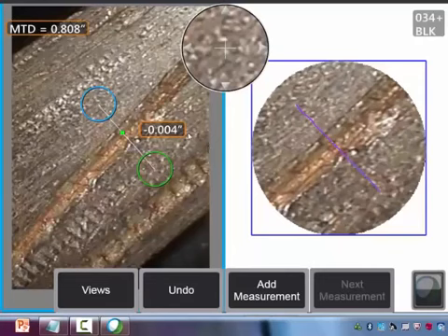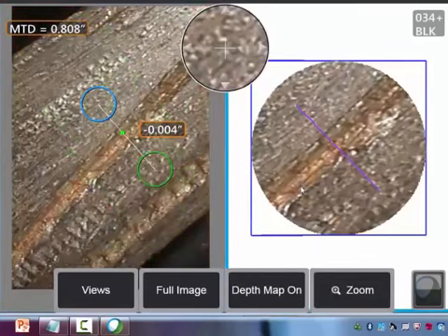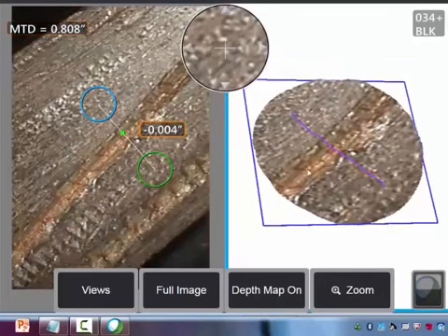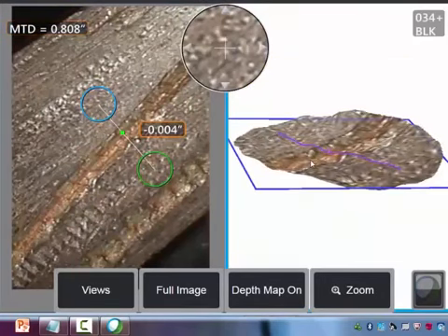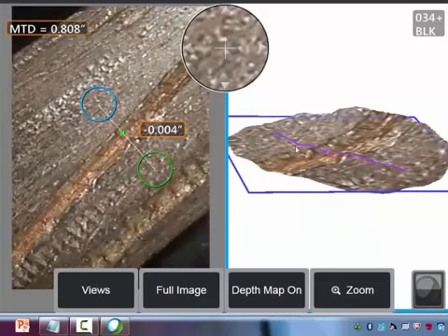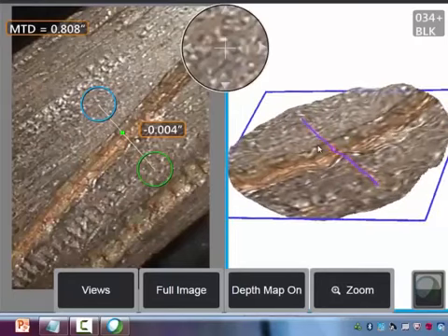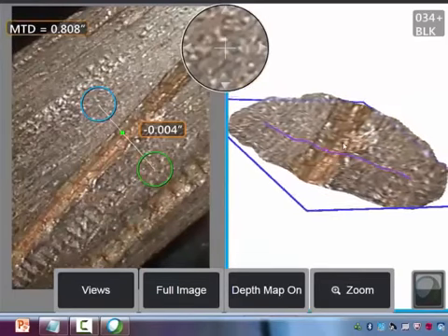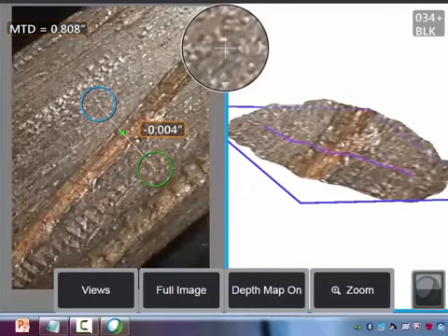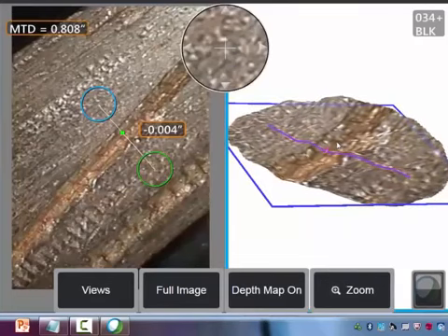So we talked about how the matching error varies from pixel to pixel in the image. And that variation causes bumps in the computed 3D surface coordinates. So if we look at this point cloud, we would generally expect the areas outside of the indication to be fairly smooth just based on the 2D image. But what we see in the point cloud view is that those areas are sort of bumpy looking. So this is the noise I'm talking about that's created from this variation in this matching error.